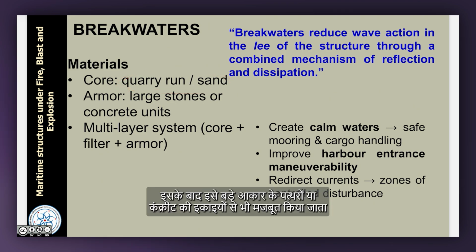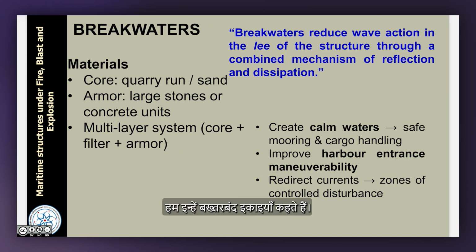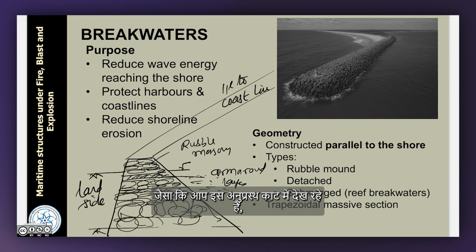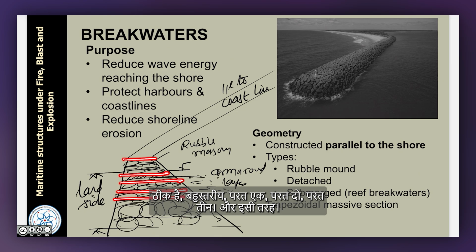Then it is also reinforced with large size boulders or concrete units. We call them armor units. It comes in a multi-layer system, core, filter, armor and so on, as you see in this cross section. Multi-layer, layer 1, layer 2, layer 3 and so on.